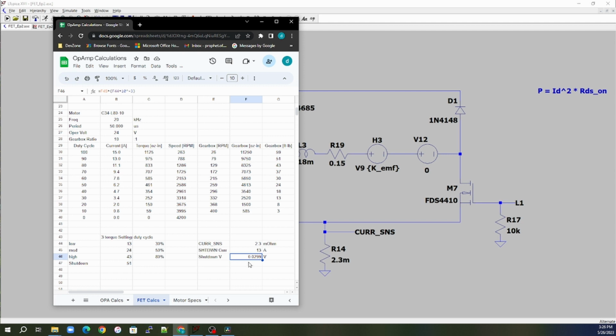Now, of course, this is probably impractical, so we'd have to go through this circuit and try to devise a better sense resistor in order to make this happen, because this is probably going to be too low. But that same microcontroller that you're using, you can have this going into an ADC, an AD converter, of a microcontroller, and then you can basically shut the motor out.